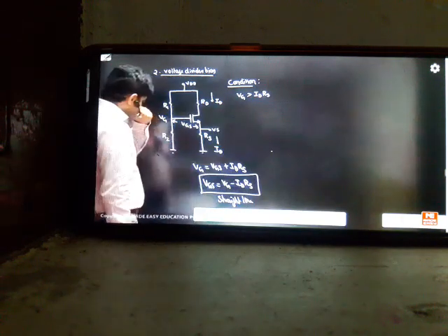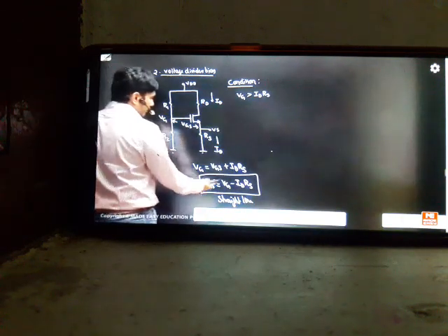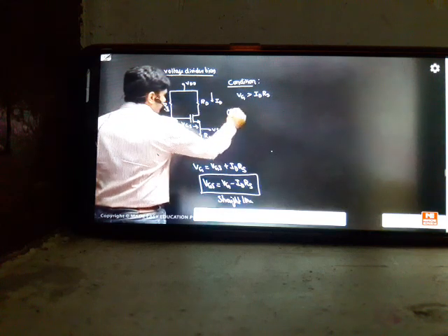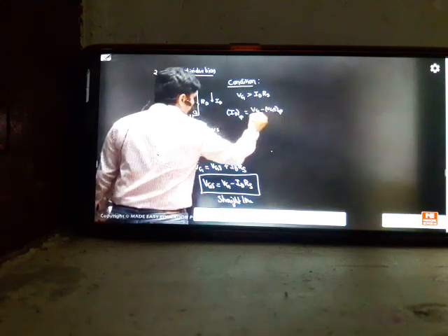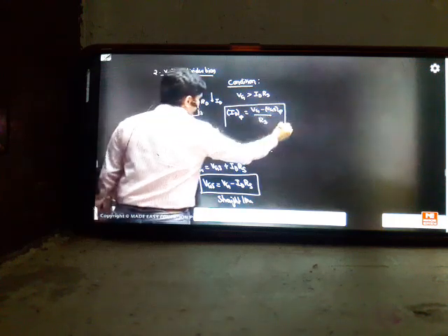So we can solve the value directly. If you want the operating current, IDQ, it is VG minus VGSQ, your top line, divided by RS. This will solve the operating point, straightforward.